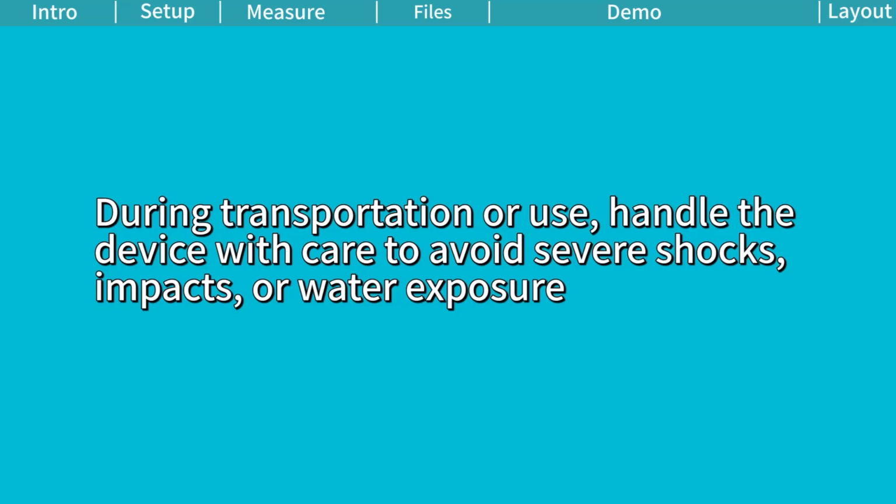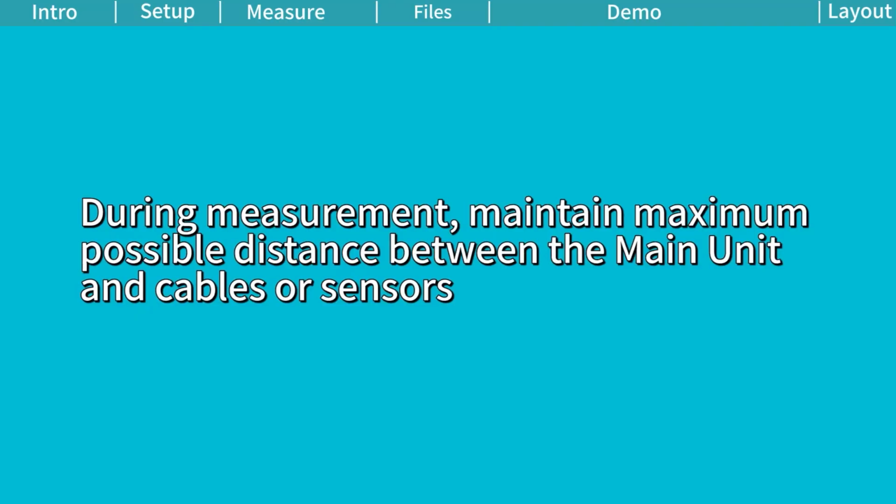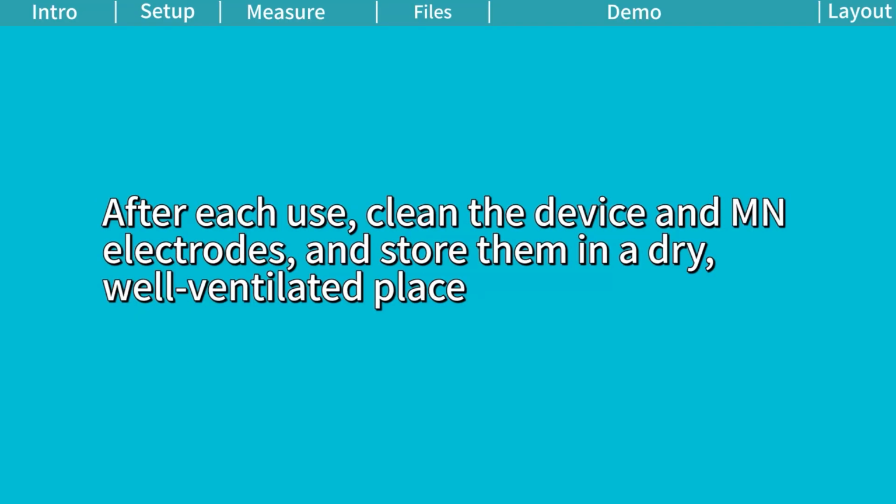Handle the device with care to avoid severe shocks, impacts, or water exposure. During measurement, maintain maximum possible distance between the main unit and cables or sensors. After each use, clean the device and M and N electrodes, and store them in a dry, well-ventilated place.